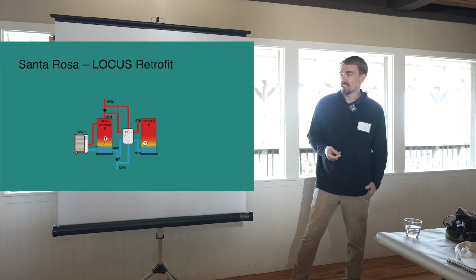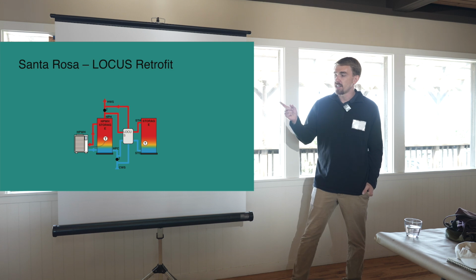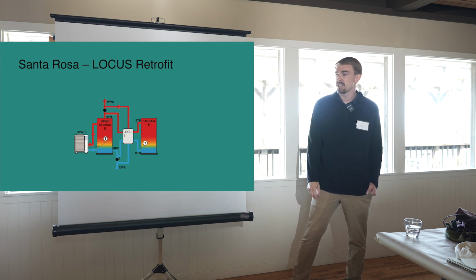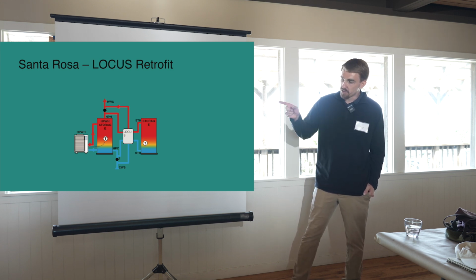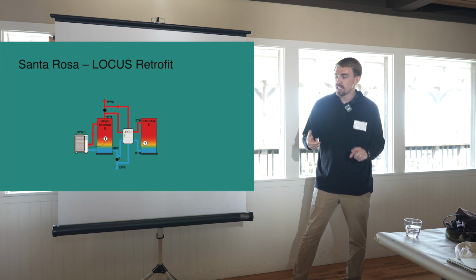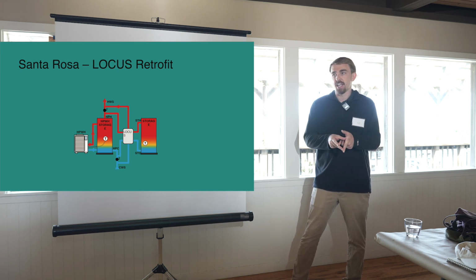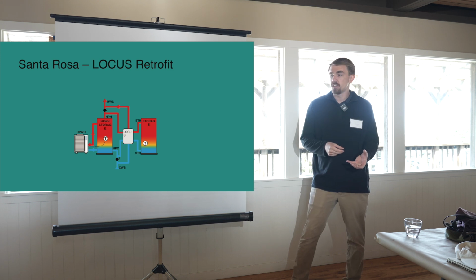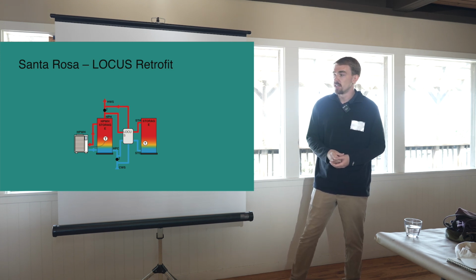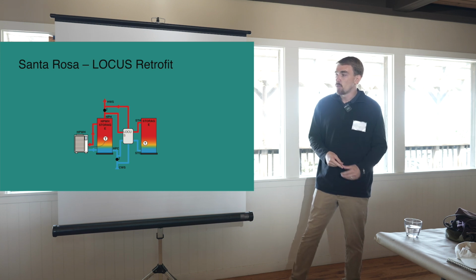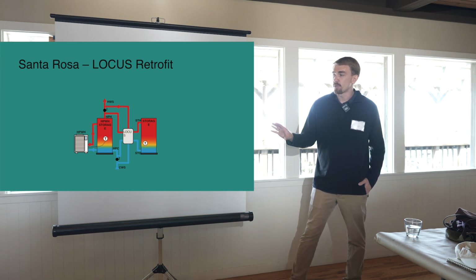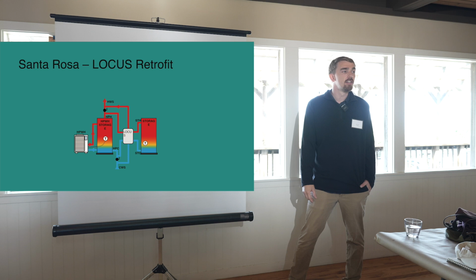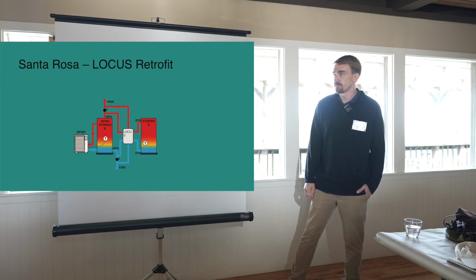So advance one more time, please. Then we're going to tie the Locus into the hot and cold connections for the building. So now, with those 2 closed ball valves, we have dedicated connections to the heat pump and dedicated connections to the building. In the other 2 buildings, we also have hot water return, so we'll have a dedicated connection to the return line as well. And advance one more time. We'll have a completely separate storage tank for additional storage that only has to connect to the Locus controller.